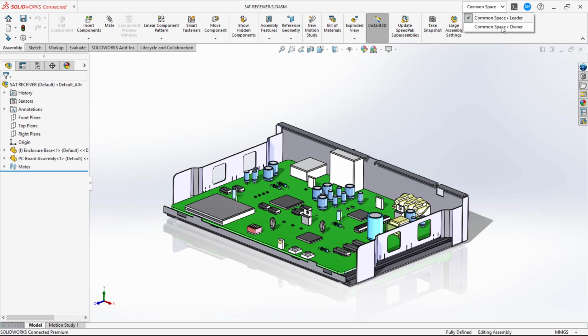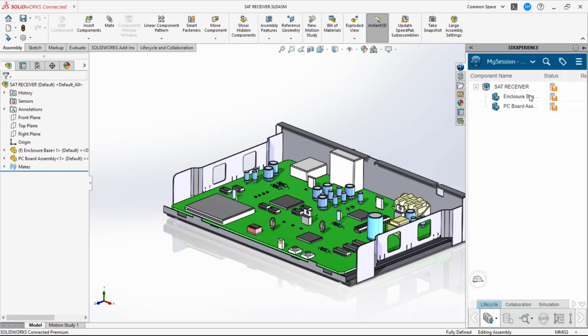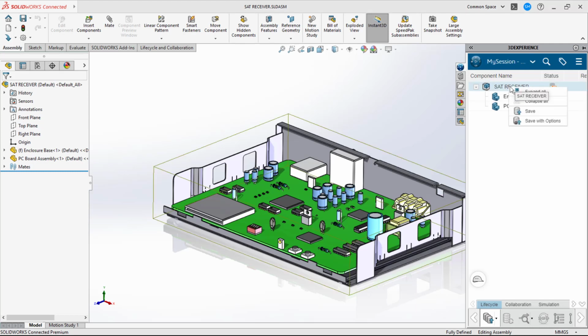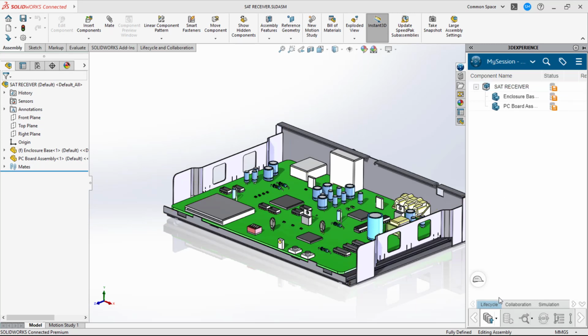As you could see in the task manager, you have it. This is the collaborative space which is newly added. If you compare to the desktop SolidWorks, it's the same: search icon, shortcut bars and all, you'll be having it here. And here you have the work offline mode and all. So this is the new thing. You could see it shows the file has not been saved into the 3D Experience. You just need to right click on it and use the save option. If you do that, it will be saved into the cloud.